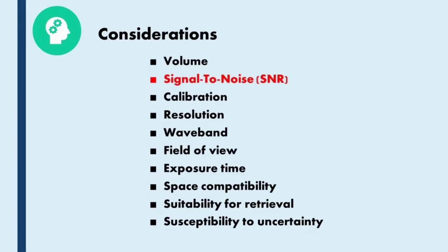For instance, signal-to-noise ratio should be at least 100. SWIR sensors are more sensitive to dark noise than the silicon-based sensors in the Viz and Pol imagers. So, they need onboard cooling, which takes up more platform resources like volume, power, and heat management. Considering calibration, the volume restricts us to vicarious methods. In this aspect, Pol imagers cause additional complexity, since beyond basic calibration, they also need polarimetric calibration.